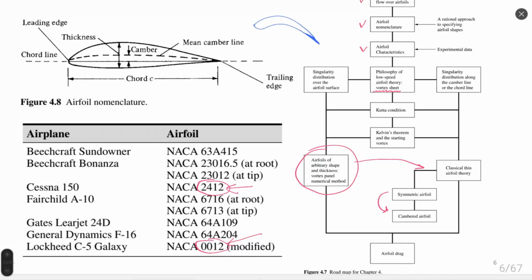So probably this thin airfoil is working at transonic conditions, because it works much better at transonic conditions than a thick airfoil. So small thickness must be used for high velocity applications, and high camber, especially to use this airfoil at a very low angle of attack, receiving a high value of lift or lift coefficient. Probably this is the purpose, but we can see.